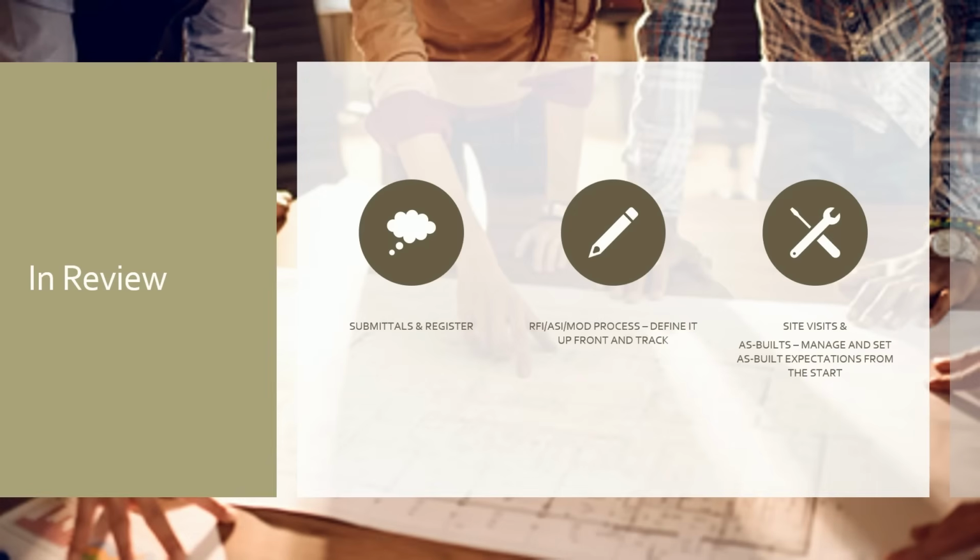And that takes us to review. So we've talked through the submittals and the register. Scrub, scrub, scrub. That's the word. Scrub those registers before they go in, and make sure that you talk about how you're going to manage them with your design team: review times, who it goes to, things like that. It's super important. RFIs, ASIs, and mods.